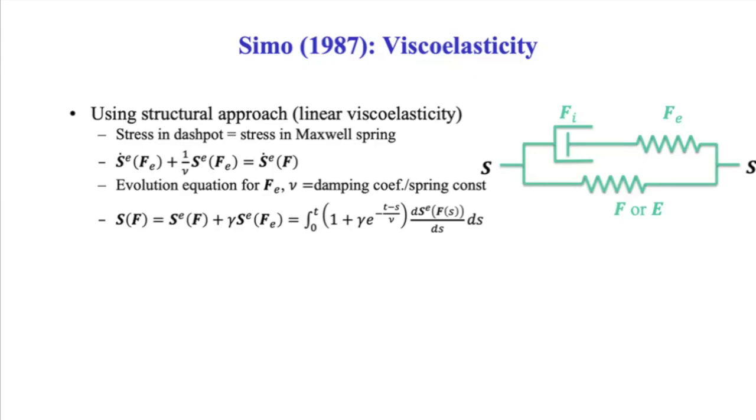What if that soft tissue happens to be viscoelastic? Some of the damage criteria that we have in damage theory are based on, for example, the strain energy that's in the material. So what is the strain energy in a viscoelastic material? What's interesting is, though the literature has proposed that there exists one, hardly anyone actually tells you how to calculate it. It turns out it's not trivial. There are additional assumptions that you have to make to calculate the strain energy of a viscoelastic material.